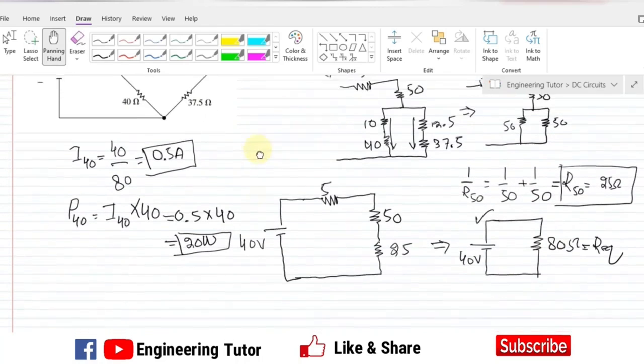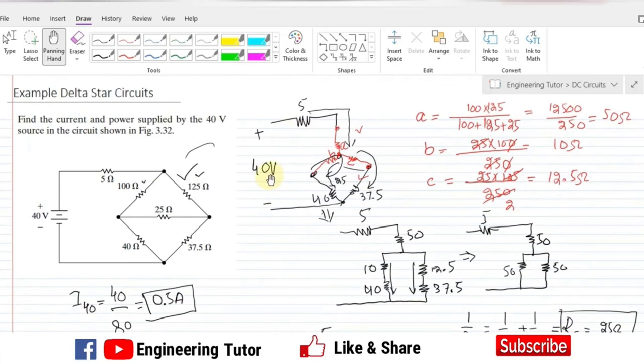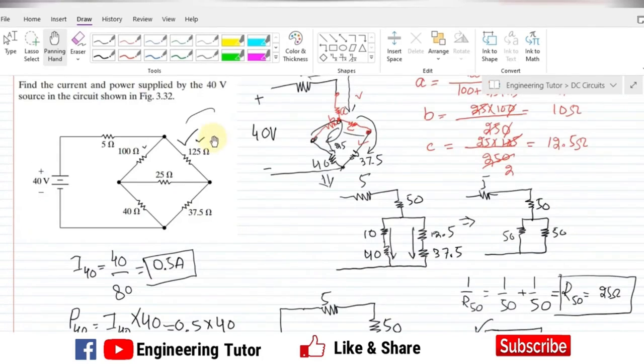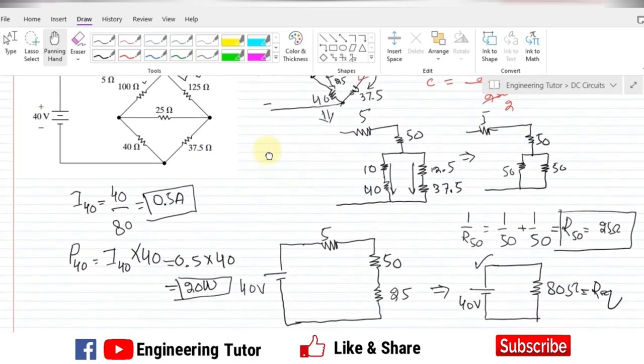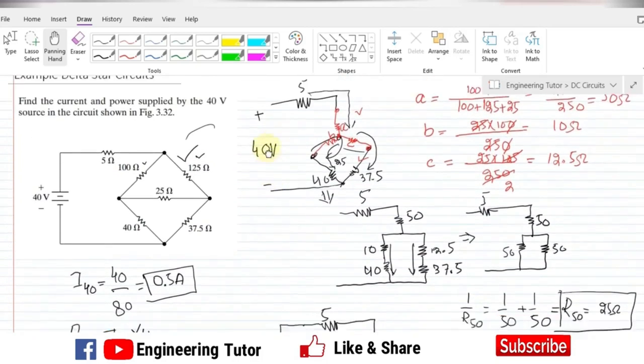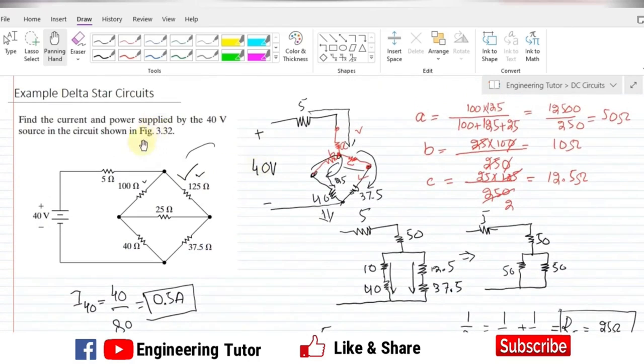Initially we have to find the equivalent resistance: pick any one of the two deltas, or any of the stars, and convert it into the other configuration. Here we have used the conventional circuit laws to find the equivalent resistance, and after finding it we find the current and power supplied by the 40 volt source.